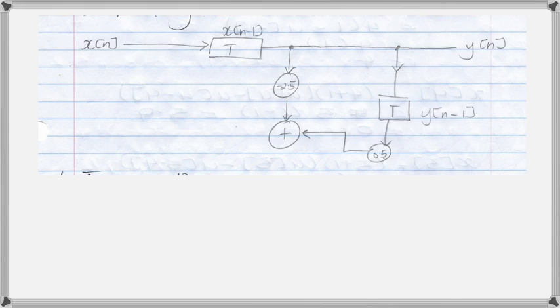Now let's look at a student's example so that we may see the difference. Can you see that what is drawn here has a different output to that? Follow where the x[n] goes. The x[n] goes through one delay period and immediately becomes the y[n]. So observe that the output is actually y[n] equal to x[n-1].